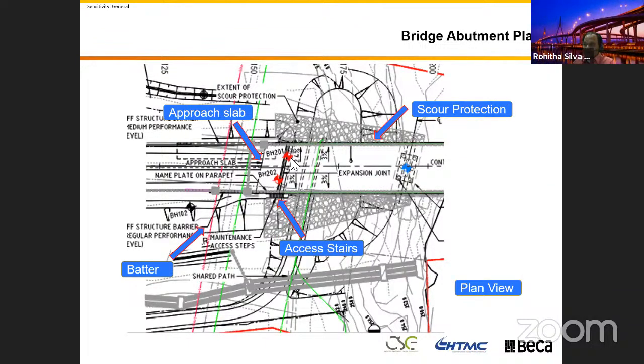So you've got this red point in here. Over here, the settlement you expect is only 20. If you expect your settlement back in here to be 200, geotechnical engineers come up with very nice solutions: build another bridge behind that one. It's about another 70 meters in length to absorb that settlement.